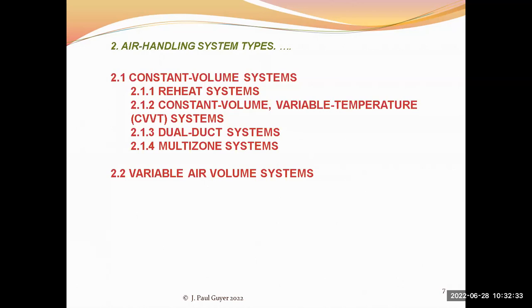And then you can put a control device, and it can be dampers on each of these 10 small ducts, or it can be little heating or cooling coils. So with a multi-zone system, you might have 10 zones or ducts. And that means that on the floor, you can have 10 thermostats.